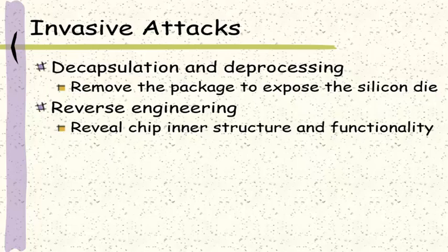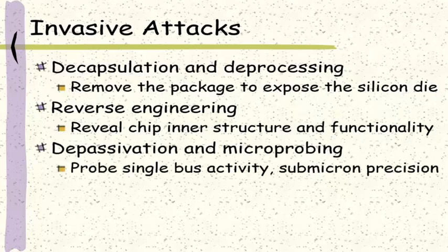In order to obtain more detailed information about the chip, a micro-probing station will be needed. This is perhaps the most expensive equipment required for invasive attacks. It can reach sub-micron precision, so electrical contacts with a single on-chip bus line can be established without damaging them. This means that the attacker will be able to monitor on-chip bus activities, and they can also inject the tested signals and observe the chip's response. For example, secret keys or sensitive data can be extracted from memory by this method.